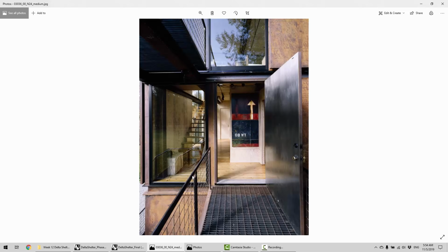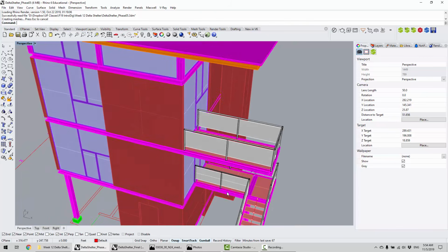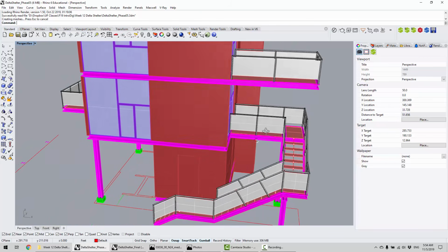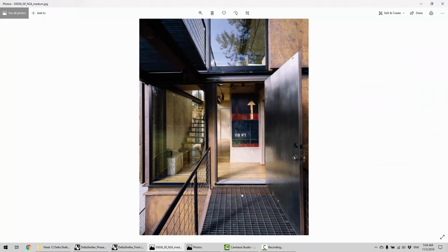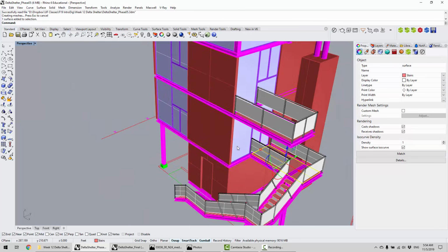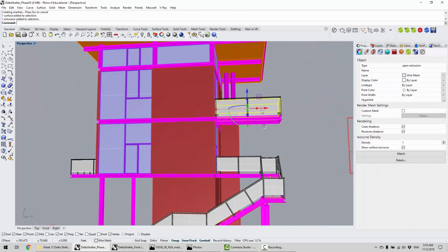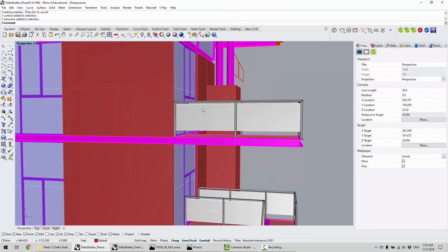But if you actually model them and pipe them, the geometry gets really heavy when you have things that are dense like this, or even the open steel floor sort of things on the decks and the balconies. If you try to model it, it's doable, but it will bog down your model a lot. So this is the type of thing I typically would treat just as a material when we get to a rendering engine. That's why they're actually just modeled as surfaces here, this and this, right? Eventually we can apply a material to it, and it will give you that open wire mesh feeling.